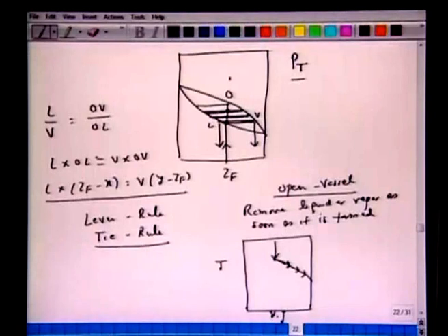There will be vapor and liquid like in the previous case, but you are just removing all the liquid. Similarly, if you start with a liquid phase, say same compositions, and as soon as the vapor is formed, you remove it, you will follow this path like this, which is same as Tb and same as T. So this is very similar to what we have in the previous case, except you are removing the liquid or the vapor as soon as you reach the dew point or the bubble point.